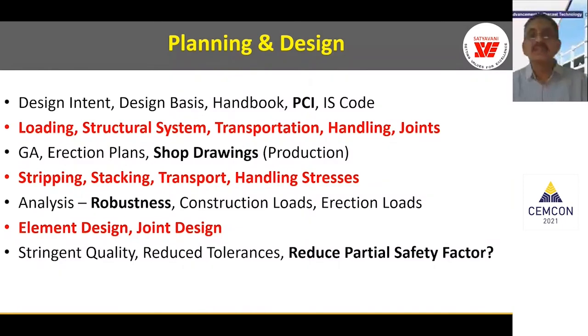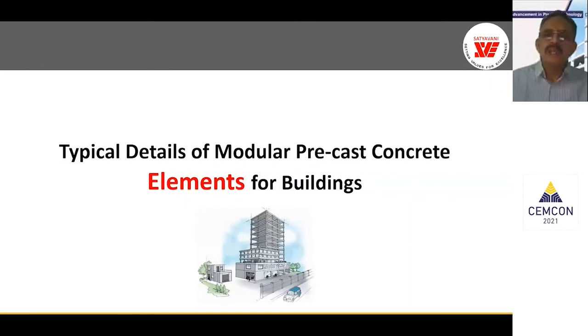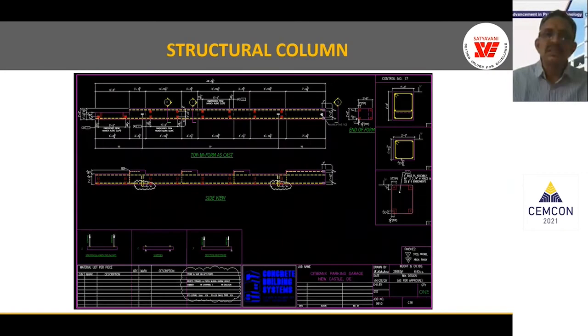But with precast, if you do the uncertainty analysis, we can save on the partial safety factors and design, which is bound to happen in future, if not immediately, maybe in a decade or so. So this will help in saving on the materials in precast when we use these uncertainty factors by using fuzzy logic.